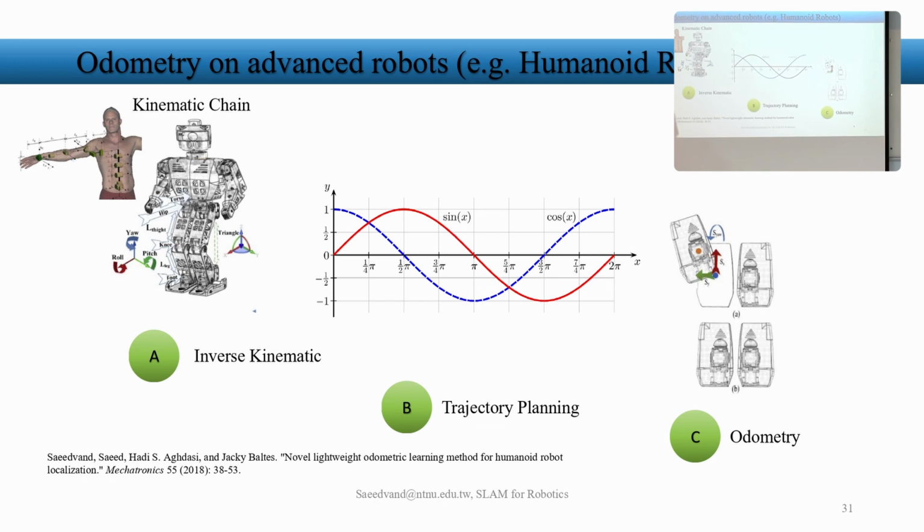What does it mean? Let's say I'm a humanoid robot and I want to control my arm. If I want to grasp this object over here with my right arm, what should I do as a programmer? For each one of the joints, I need to send some position so that my arm reaches here, right? But isn't it too hard? Because in 3D workspace, how can you say what the position of this joint and this joint should be to get there? Too many parameters.